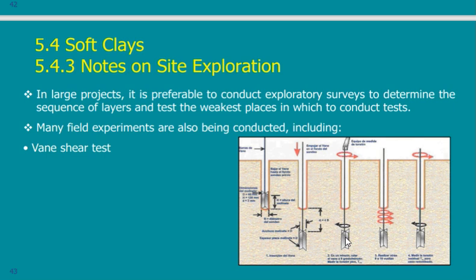The stronger the soil, the harder it will be for me to rotate this. Imagine that this is immersed in very good sand, you cannot move it. If it is in good clay, you will have some difficulty. But if it is in soft clay, it is like putting a spoon inside a soup. It's nothing, it goes very easily. So we rotate it, 90 degrees, 360 degrees, and once we rotate it, we calculate the torque that we needed for this action.